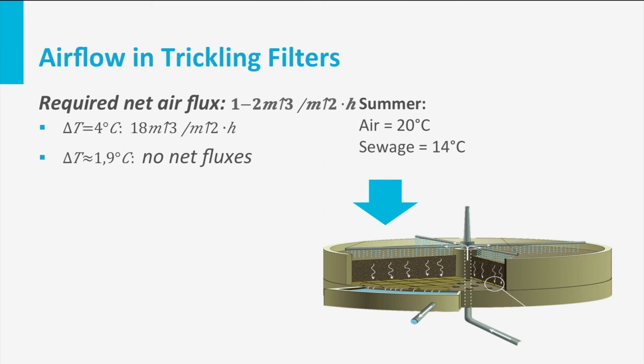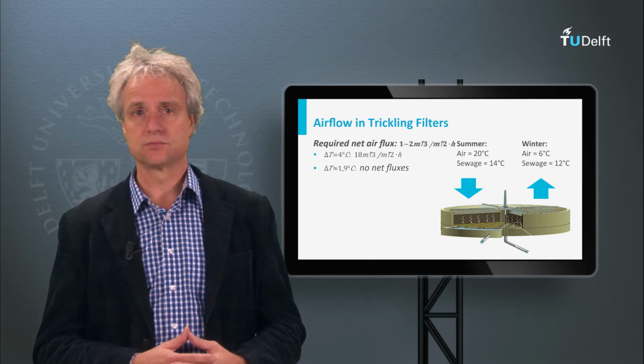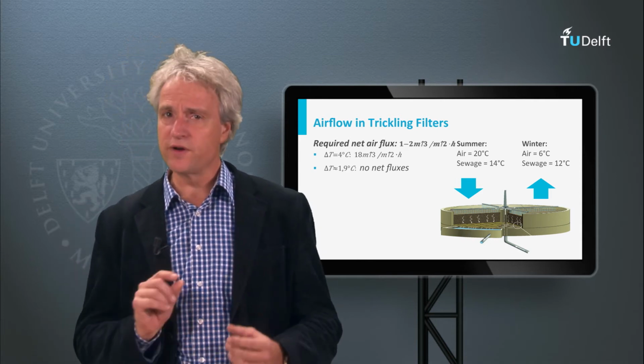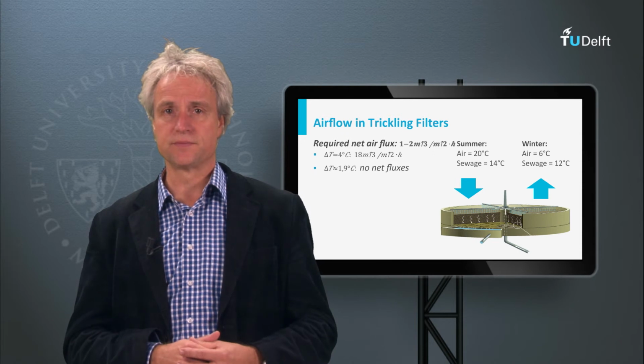The airflow takes possible odorous volatile compounds in its downward flow. The odorous compounds are subsequently oxidized in the deeper parts of the bed. In reverse situations, so when the air is colder than the sewage, an upward airflow can be expected and thus a more smelly trickling filter. An adequate airflow is already obtained with very little temperature differences.